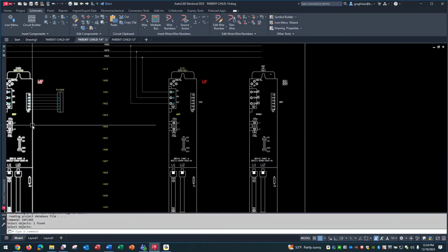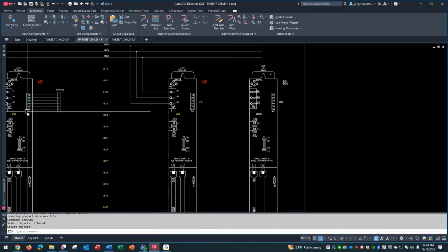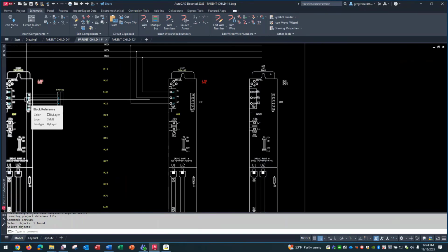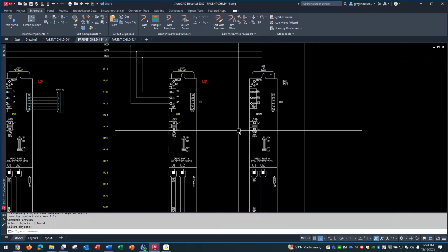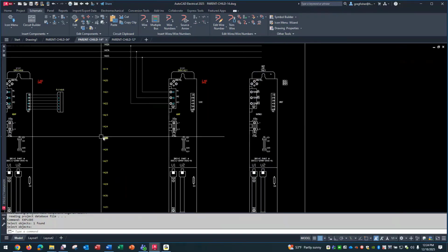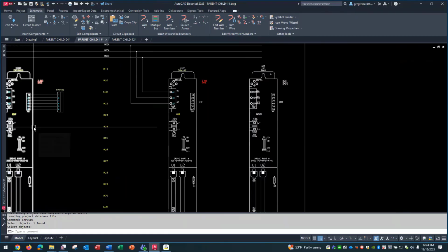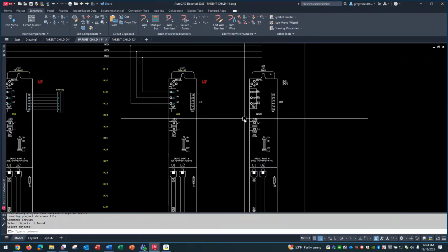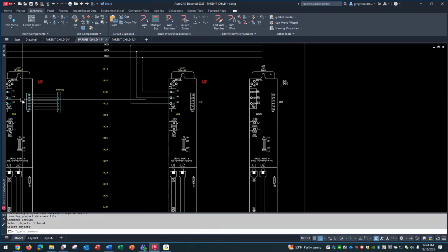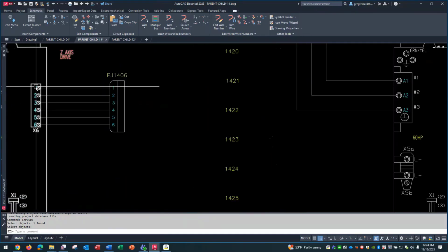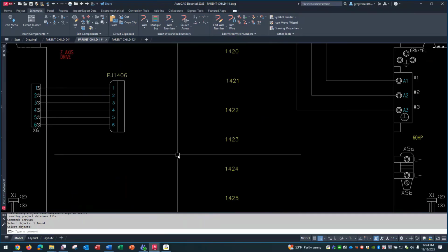And as I mentioned, with this one, all the connection points for that X6 connector are already there. On the child symbol, they're not. So when I created the parent-child setup, I just basically copied this symbol like I did on this one, exploded it, and erased the connection points that are associated to it.